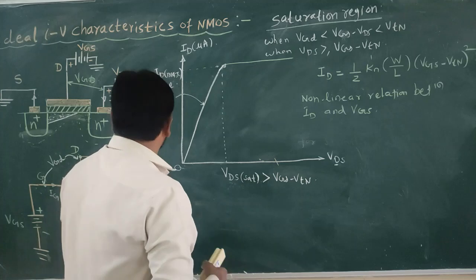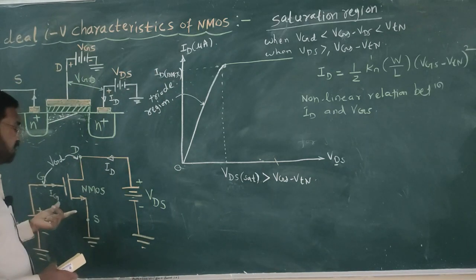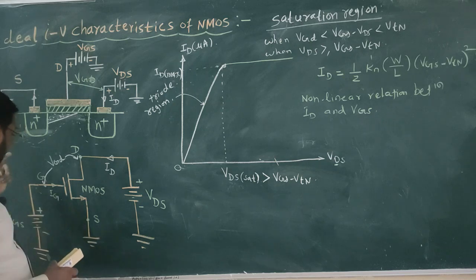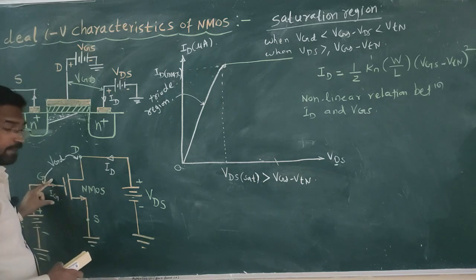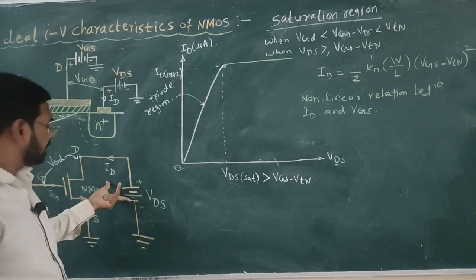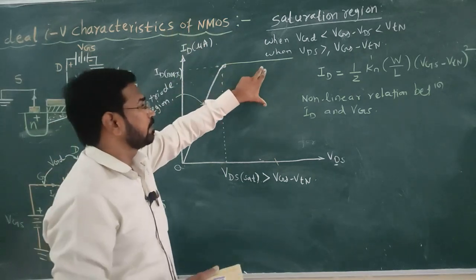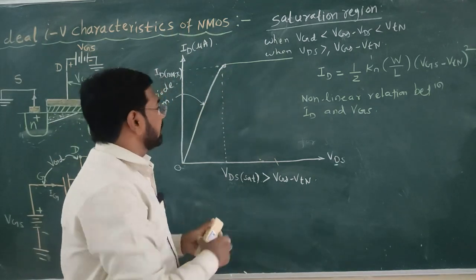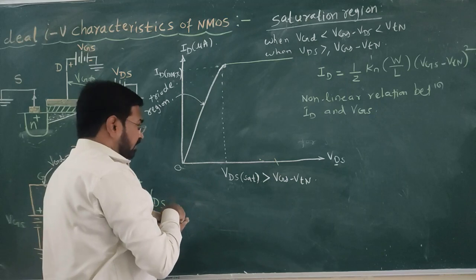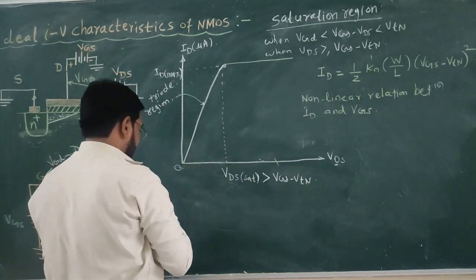But here it is not the input current going into the device, only the gate voltage is changing and the drain current correspondingly changes. We want this kind of relation in the device, and here we can obtain that relation. If you change VGS in this equation, you will get one more characteristic.